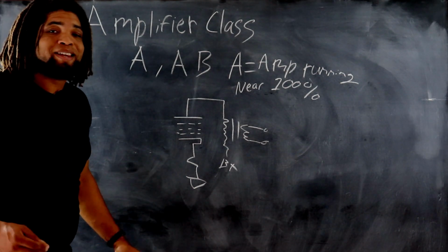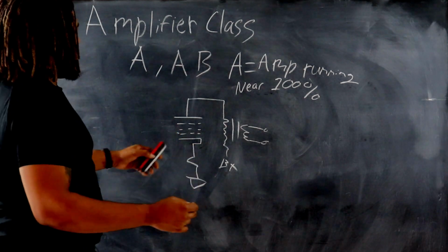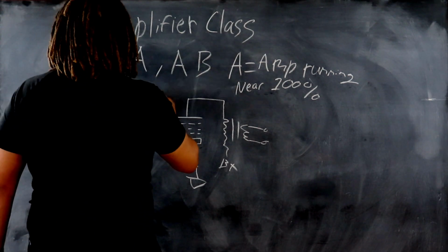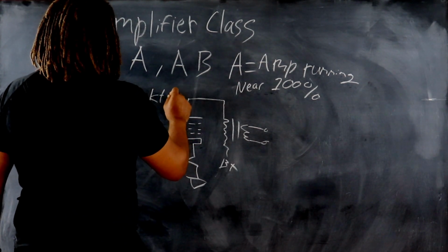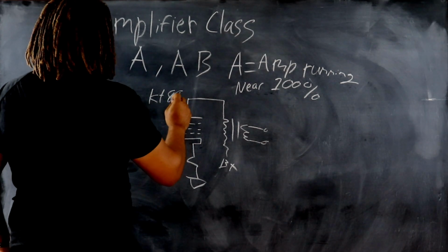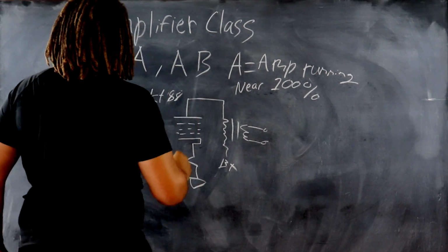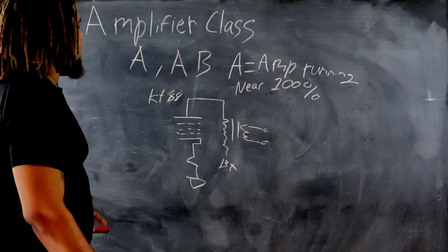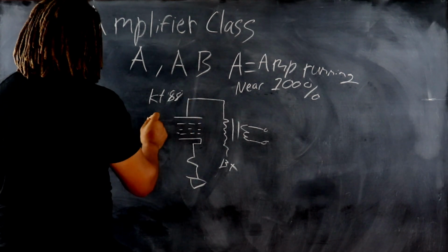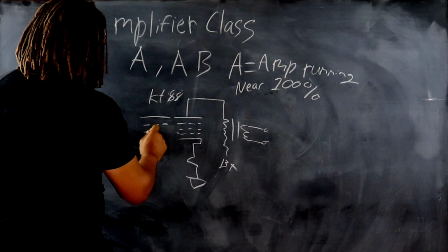And this is where it gets inefficient in the vacuum tube world. Let's say I want to make a 60 watt amp and I can get 30 watts out of a KT88, but I want to make a 60 watt Class A monoblock. Well, what I'm going to have to do is parallel this tube with another.